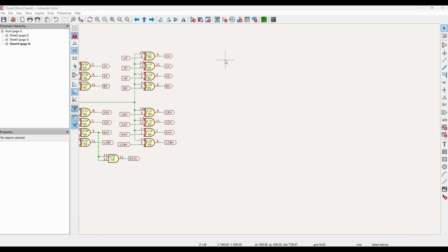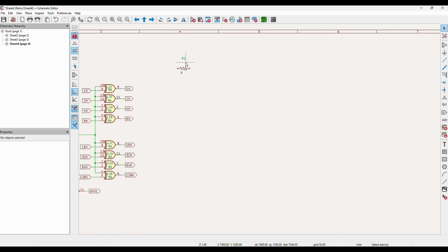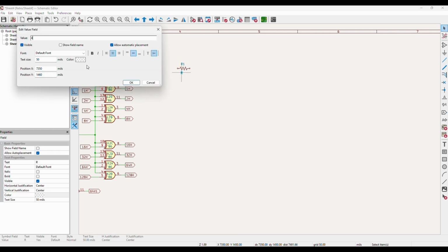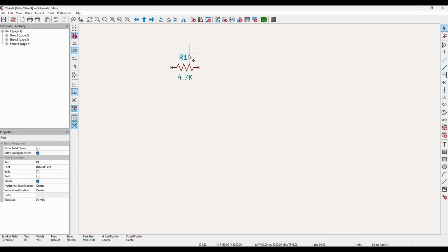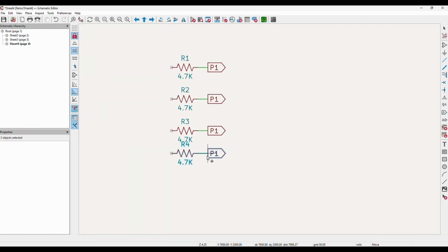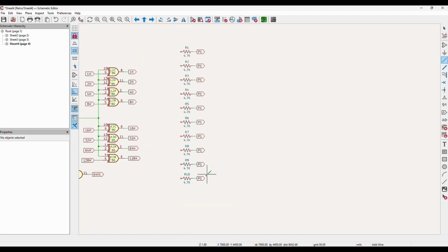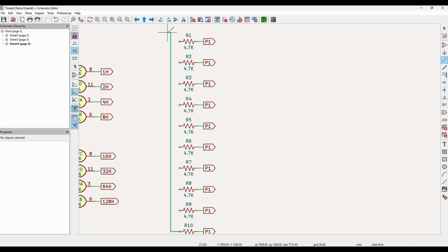While we're in here, we might as well add these pull-ups. And remember, we're going to specifically name these lines per the pull-up resistors, and also use the proper pull-up nets throughout the schematic. For the breadboard, we're just throwing in resistors wherever we need something pulled up to reduce our rat's nest. On the retro board, we'll match the legacy pull-ups and add any pins they left floating.